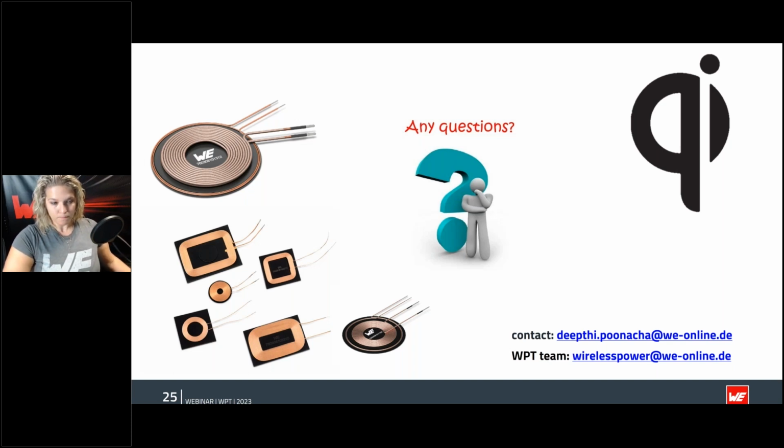When you bring up a system with both technologies inside, you have to make sure you have a good operating point, which is defined by the coupling factor between the receiver and the transmitter coil. This is again defined by the separation distance. At a particular distance, the NFC technology might not work so well, so finding that sweet spot between the two technologies is very important.